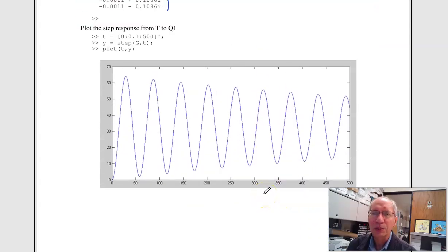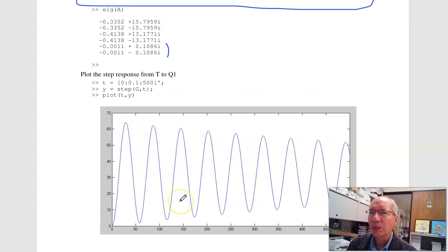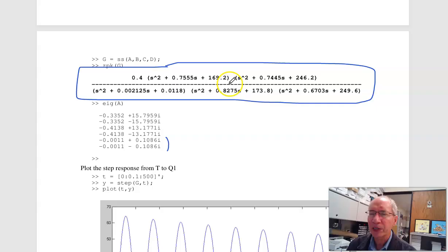And that is homework set number 6 for ECE 461. The point behind the homework set is whenever you see a transfer function, think about the different systems. If you have real poles, that's like an RC circuit. Complex poles, RLC circuit, or mass spring system. The math doesn't care. Any system that has the same transfer function behaves the same. It gives you an idea of something to think about when you see problems later on in the course. Homework set 6 for 461.